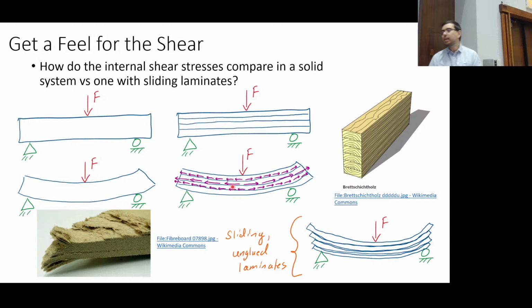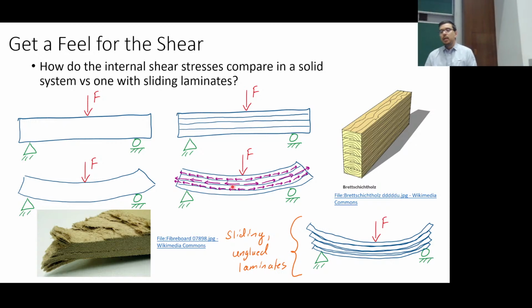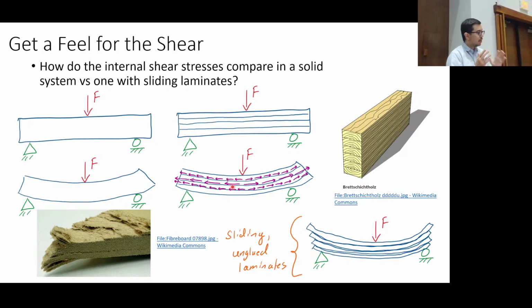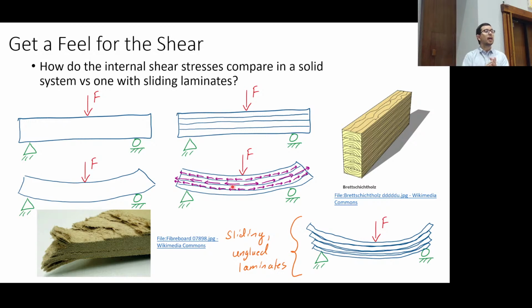I said last time that cables are great because the bending stresses are 0 at the neutral axis, and you can leverage that quite a bit. In reality, you can have failure due to shear internally as well. Once again, though, as we'll see, as the length gets larger and larger for these beams, the shear stress becomes small compared to the bending stress.